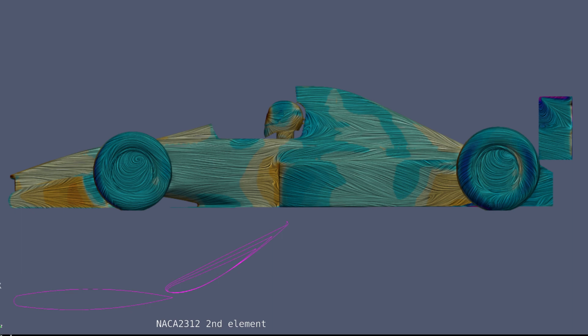To try and make things better, I then created a custom second element profile more in line with the images with a larger round on the leading edge. It seemed to match the main element better and added 60 newtons of downforce for 10 newtons of drag. What's actually happening here is the main element has an unusual upper profile due, I suspect, to structural reasons. It is rather thick and tapers to the trailing edge later than is normally the case. Therefore, the angle of attack for the second element may be a bit high.